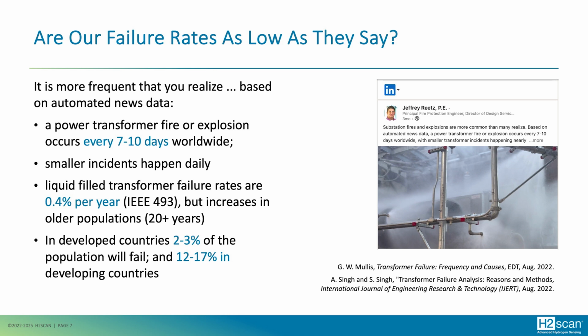That's a fire or explosion. That's the one that is spectacular. That's the one that draws a lot of publicity. But smaller incidents happen multiple times daily. And as I researched a little further, I found the liquid-filled transformer failure rates are 0.4% per year per IEEE 493. But that's only good as populations approach 20 years. After that, it goes up exponentially.